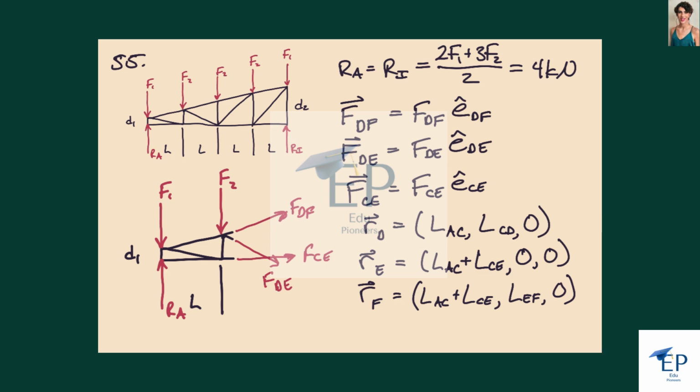So what we can figure out is the reaction forces. Because of the symmetry in this system, the reaction forces have to be the same, and they have to offset these loads. So that means that they are going to be 4 kilonewtons each on each side here. And then one side is pinned. This side is pinned, which basically means the horizontal reaction on that side is 0 because there's no applied horizontal loads. And so in the first case, we're asked to find